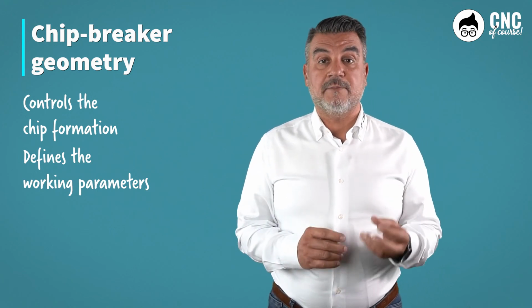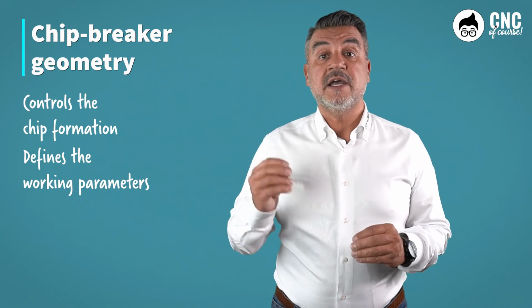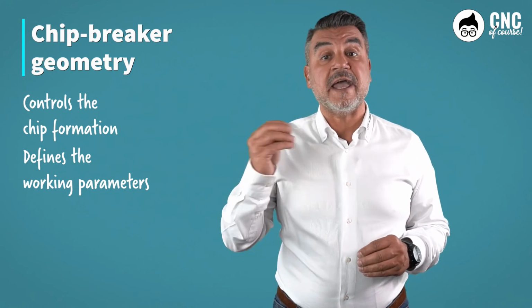So we will choose one geometry over another depending on the material to be machined and the type of machining. If we are going to do roughing where the depths of cut and feeds are high, we will choose a geometry that is suitable for the purpose. But if we use the same geometry in side finishing, we will no longer be able to control the chip. And frequently in these cases, it would create a very long chip wire that could distract us and be dangerous for the machining safety. So it is better to thoroughly study and consult the geometries of your insert builder